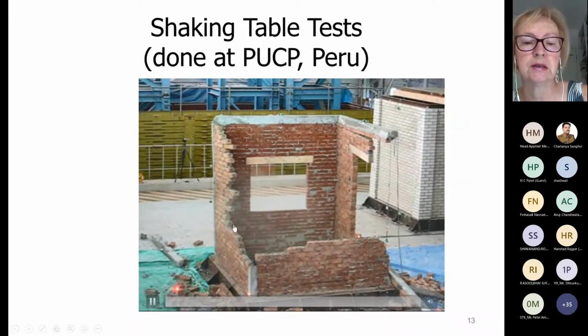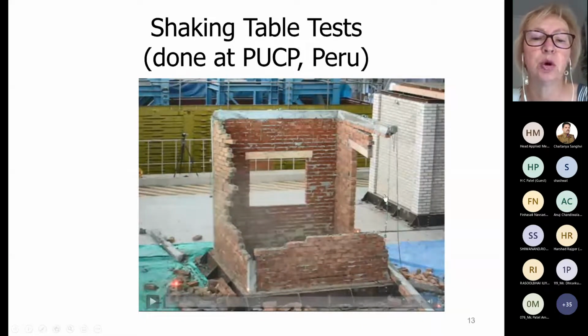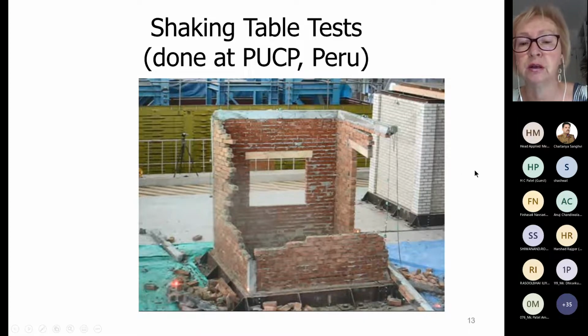But the wall thickness is 110 millimeters, and that is the same size as the tie columns. And you can see also that we don't see any reinforcement. I guess there is reinforcement in the tie columns hanging there, but it's very small size. They still had 4 bars, but it is not a very good practice. Still, not too many confined masonry buildings collapse in Indonesia. In fact, that is probably a reason for not-so-high death tolls in their earthquakes.